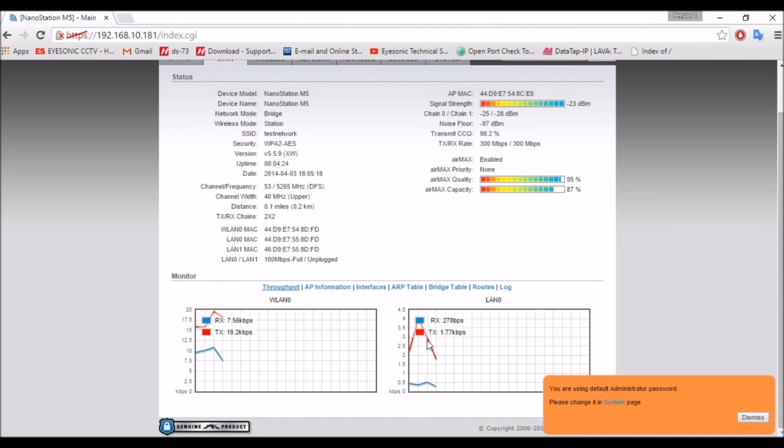The signal strength bar is really just a quick indicator. But it's a good way if you're putting up the device to sort of see, am I getting a good signal? You can always log into this while you're setting it up, just to sort of test it and make sure you are getting good signal strength. I always recommend doing the access points first for that reason.